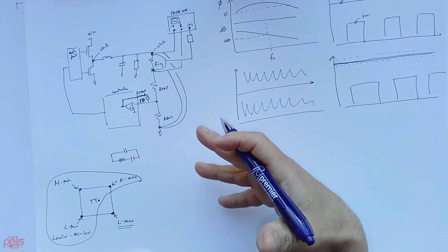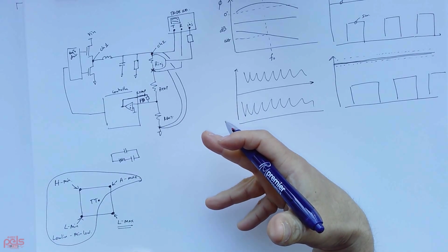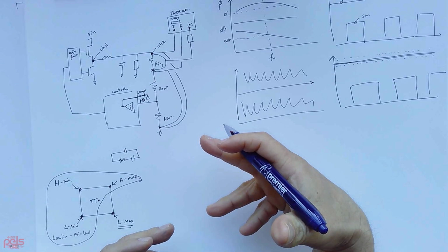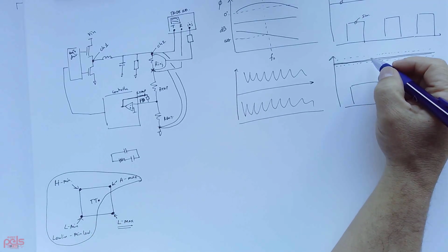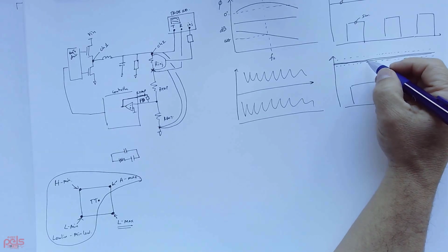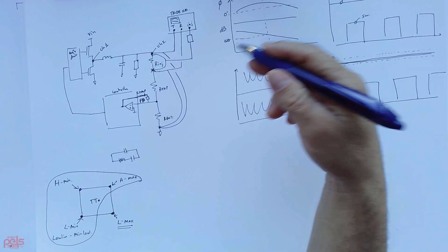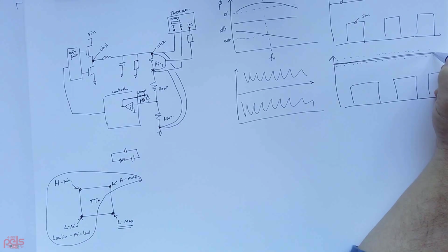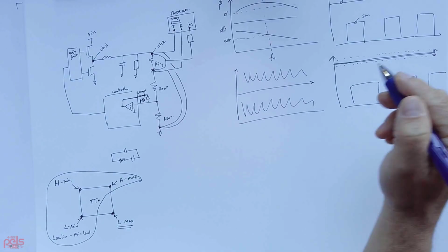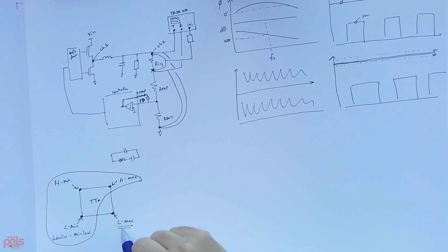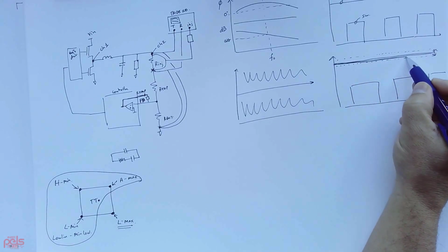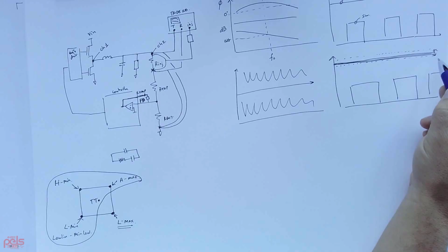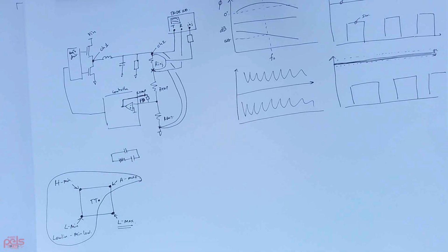It means that the power supply is still working the way it's expected to work. Typically I use plus minus 5%, at least for this particular application. This variation here was plus minus 5%, and for low line maximum load, the output was still within the regulation limit. So that didn't pose a problem.